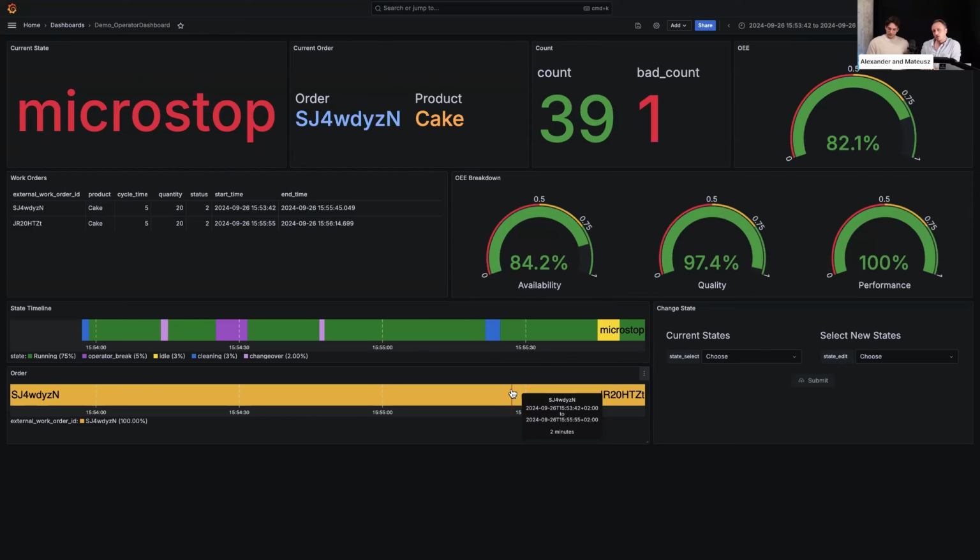But alternatively, what we're currently also working on is a historical database to Kafka bridge. So whenever we update the database with new values, we then also update Kafka, just to ensure that you pretty much have the live data in your central data source of truth. We really believe that this unified namespace is also extending to the database. And we already bridged MQTT to Kafka to have both technologies available on the same data set. But Timescale, we're only pushing it in. To really make this one place to put all your information in, it should also be pushed back to the event hub, to the MQTT and Kafka broker, to really synchronize all the data on the shop floor.